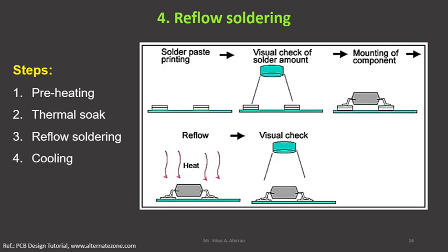instead of the adhesive or glue applied to the component, a solder paste which itself consists of flux is applied to the pads where the components need to be soldered.